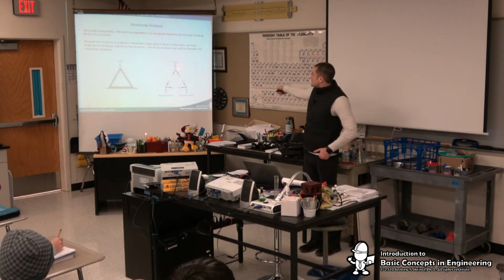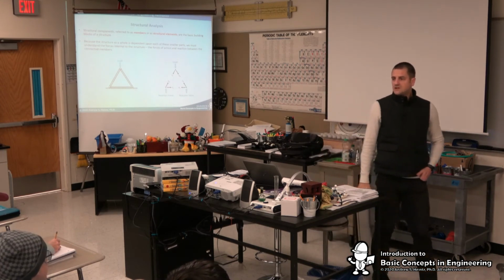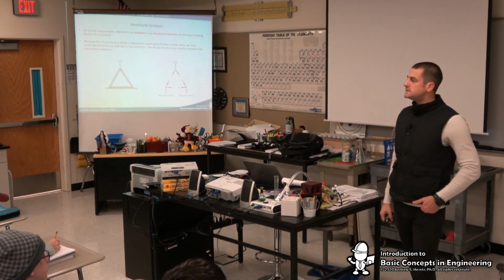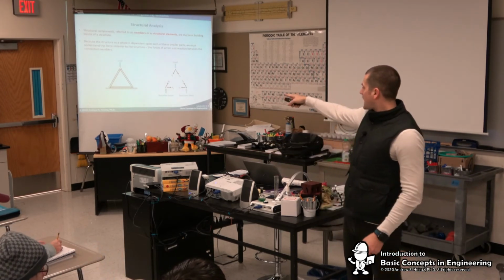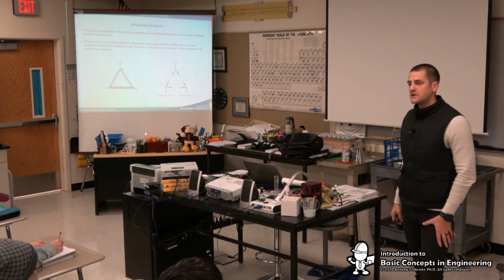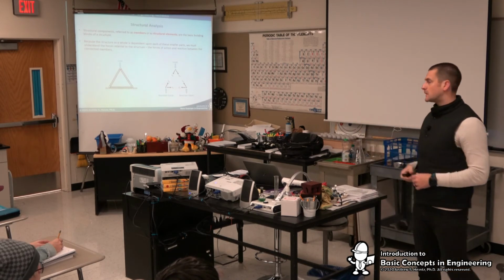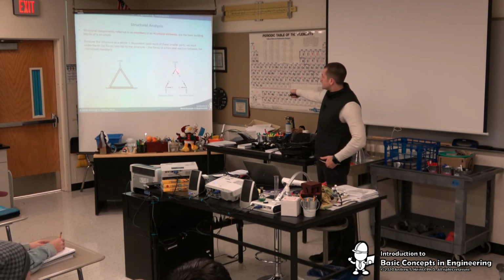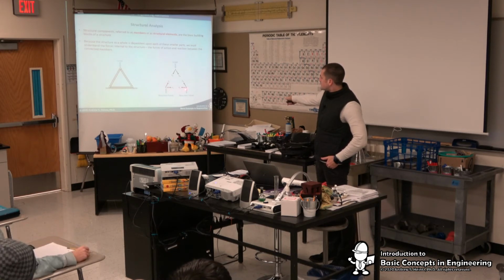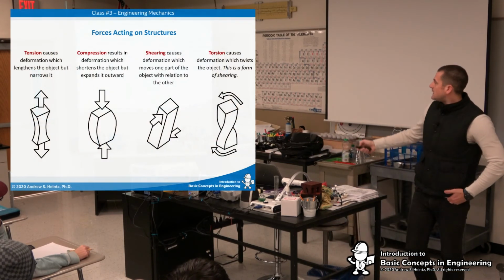If the load's going this direction, this member right here, is it under compression or tension? Why? It's being pushed, being pressed, being squished, right? What about the guy on the bottom? Is he under compression or tension? Why? He's being pulled apart, right? So you have a force pushing downwards here from the load, a reaction force here pushing upward, and then a transmitted force within the bottom member.